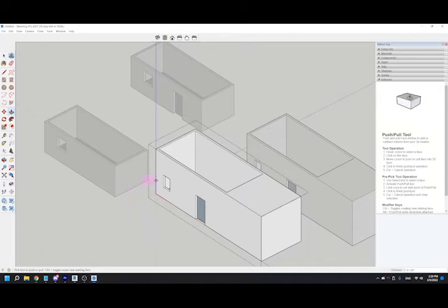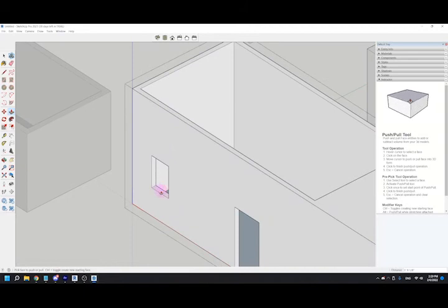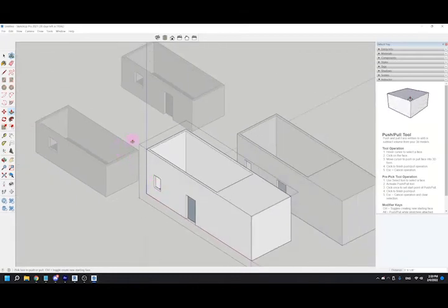Versus if I had detailed the framing components of the window sitting here in this rough opening for a window, I can just change that one window, and every time it's used in my building, it could update. Versus groups are great if it's just one feature that you don't need to have repeating over and over and over.